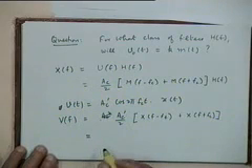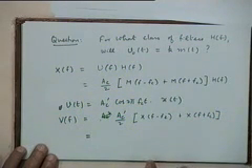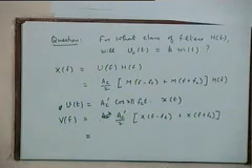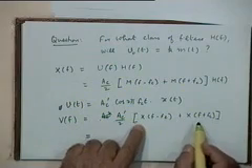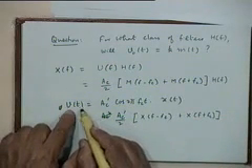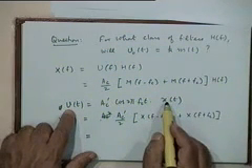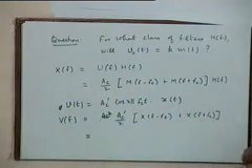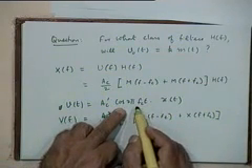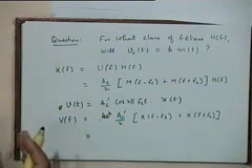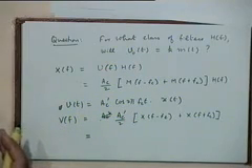So now out of these 4 terms, can I identify the 2 terms first, which will be in the baseband, because this is a band pass signal, isn't it? This V of t, sorry, this X of f is a band pass signal. That's a modulated signal. When you are doing frequency translation of that, you will get a component translated around the 0 frequency and a component translated around twice the carrier frequency. So can we identify these 2 parts separately?